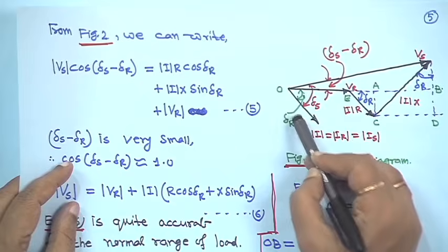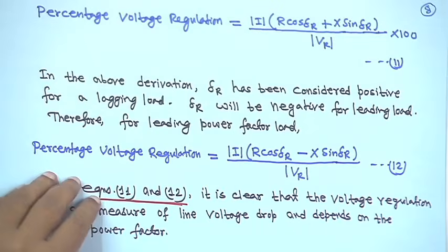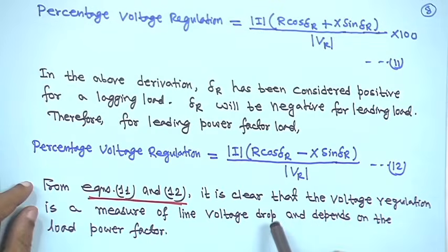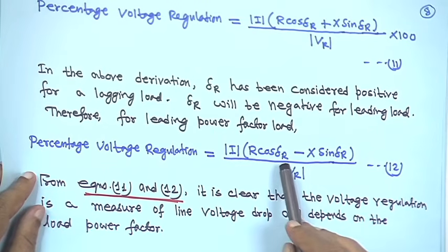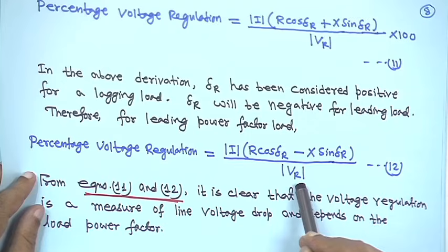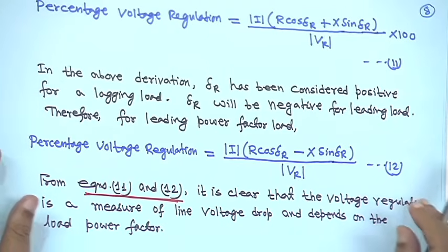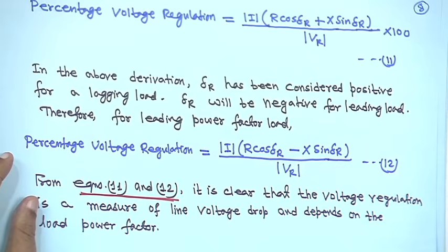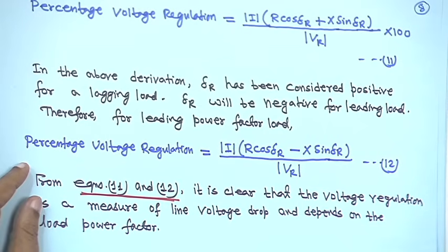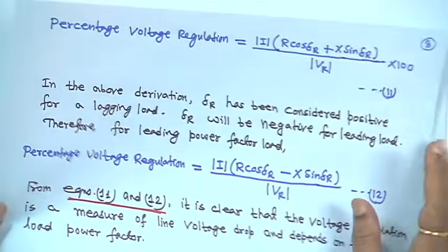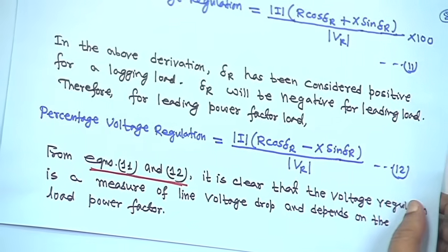This green color is delta r, which means this depends on your load power factor, right. So, basically it is the load current angle delta r and the receiving voltage. It depends on this equation 12, and this is for the short line. We will derive all these mathematical expressions for the short line, medium line, and long line. After that, we will see the numericals, right.